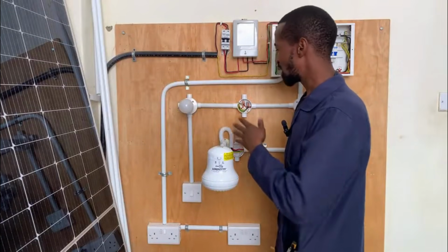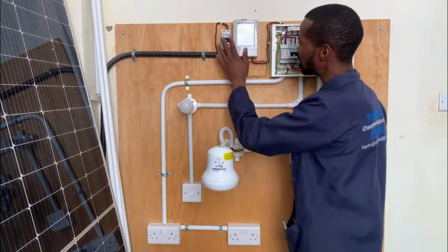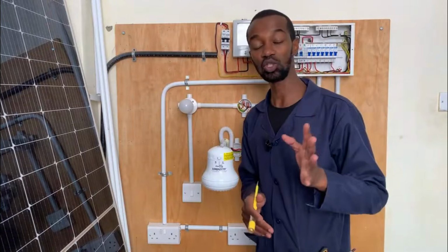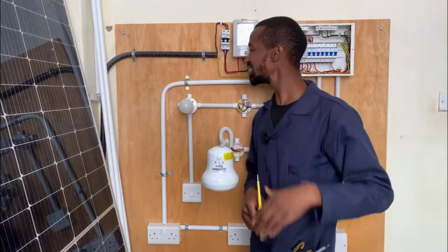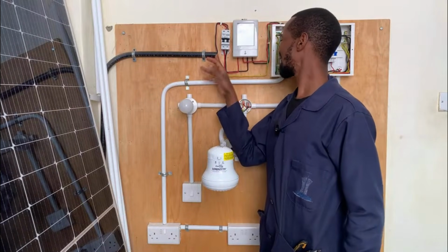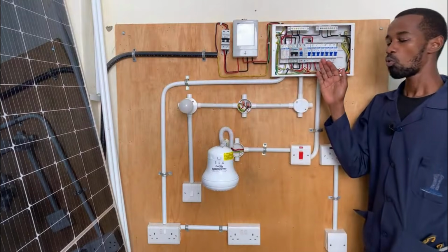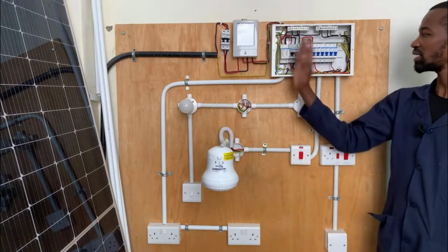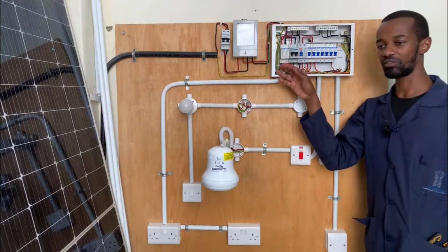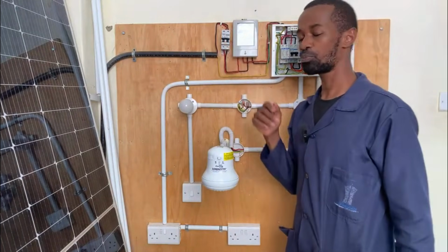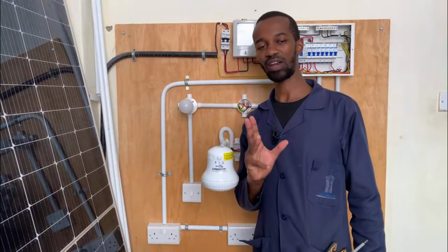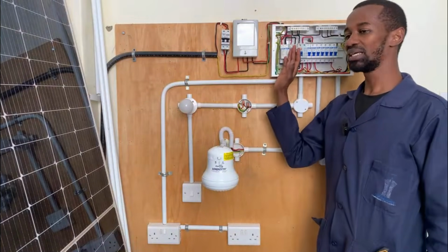Means a lot. Now, when it comes to this, we have an MCCB that is right here. This acts as the main switch or the isolator. It is at the meter box simply because it is supposed to isolate the entire installation. Now, when you have visited a customer and there is a problem in the house, let's say there is a very big issue, maybe even fire, this is the safest point for you to isolate electricity. Let us isolate electricity in case there is flooding or fire, so that we can deal with other issues.